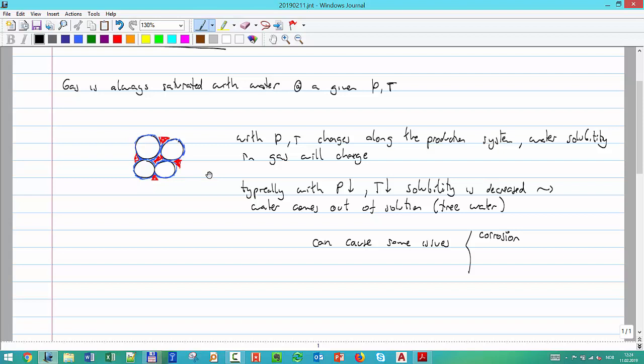Okay, if we have water in contact with metal, unprotected metal, then we can have corrosion. Corrosion causes the reduction in thickness and eventually causes a leak, which we don't want. We are very afraid in the oil industry from a leak. Okay. We can have also a problem called hydrates that we are going to see if we have time today to cover through it. But basically, this water reacts in the gas in a way that it causes something like a blockage, like an ice.